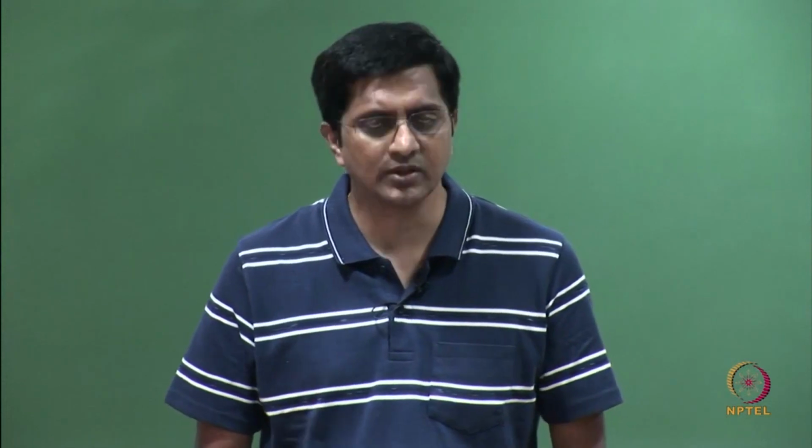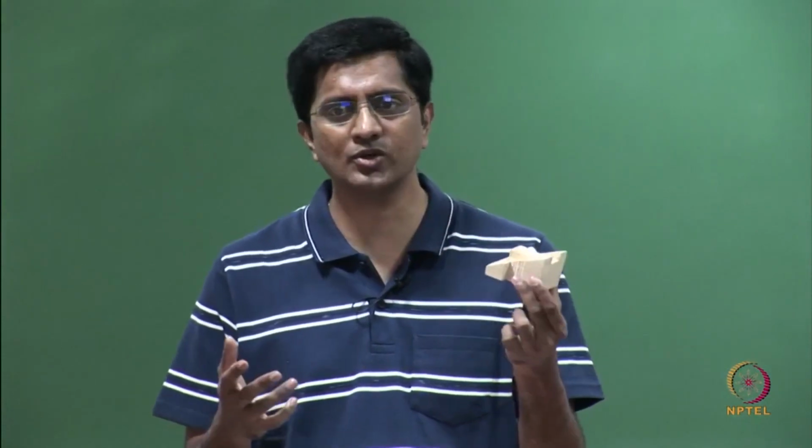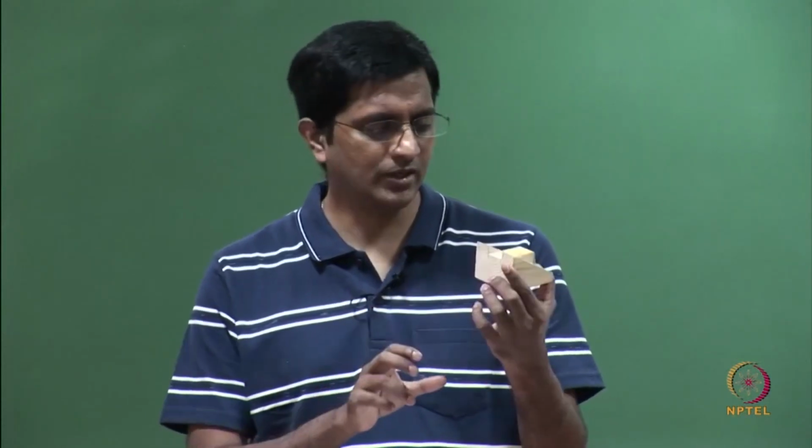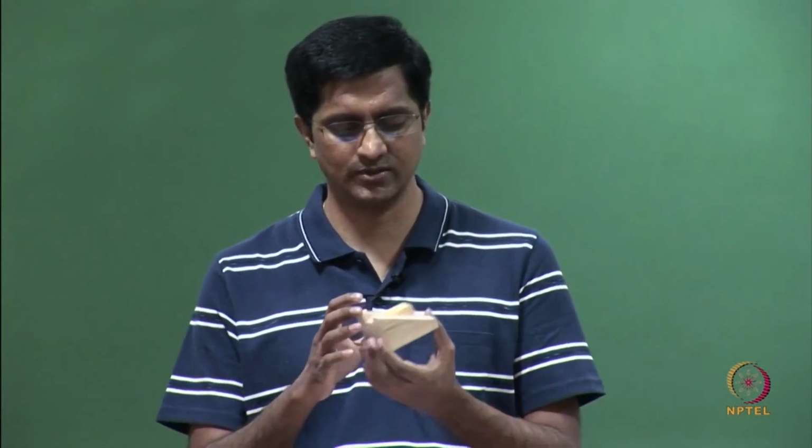So, to start with, let us say I have an object like this, and I am asked to make the engineering drawings of this object. So, I need to decide which view I will consider as a front view. What is the guiding principle? We said that the front view is a primary view that captures the most features.